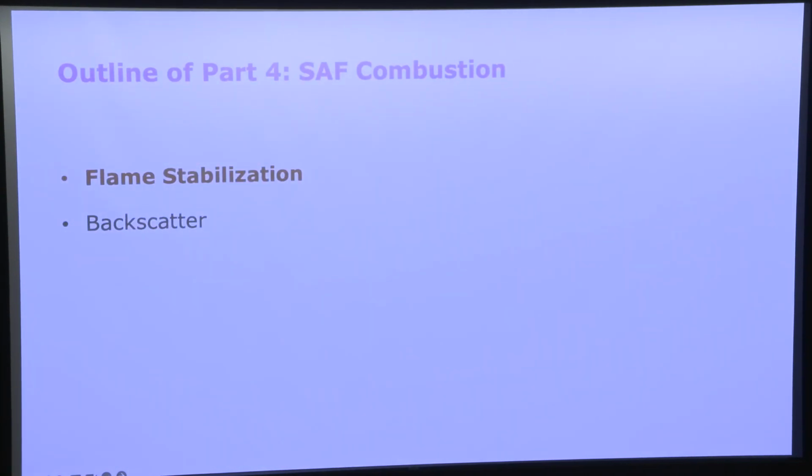So the first part of my talk here is going to focus on flame stabilization. And then towards the end, I will touch upon what happens when you generate gas expansion at the flame scales due to heat release rate, especially in conditions near lean blow-off, where you have lots of extinction and reignition happening locally. That could lead to an inverse cascade.